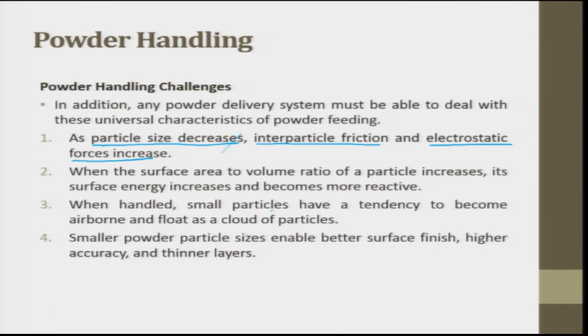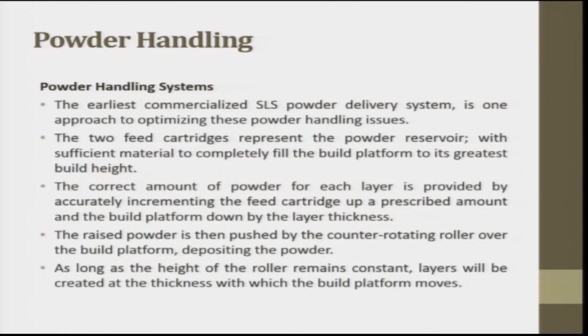When handling, small particles have a tendency to become airborne and float as a cloud of particles. So we should be careful. Smaller powder particle size enables better surface finish, higher accuracy and thinner layers. This is an advantage. But it is also a health hazard, which you have to make sure to manage.